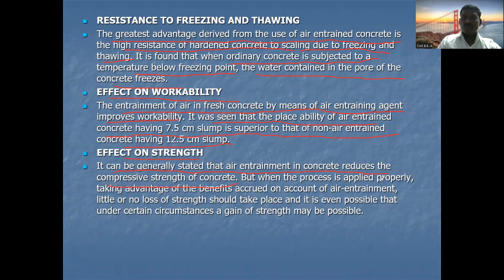But when the process is applied to this concrete, taking advantage of the benefits that occur on account of air entrainment, no loss of strength should take place, and it is even possible that under certain circumstances a gain of strength may be possible.